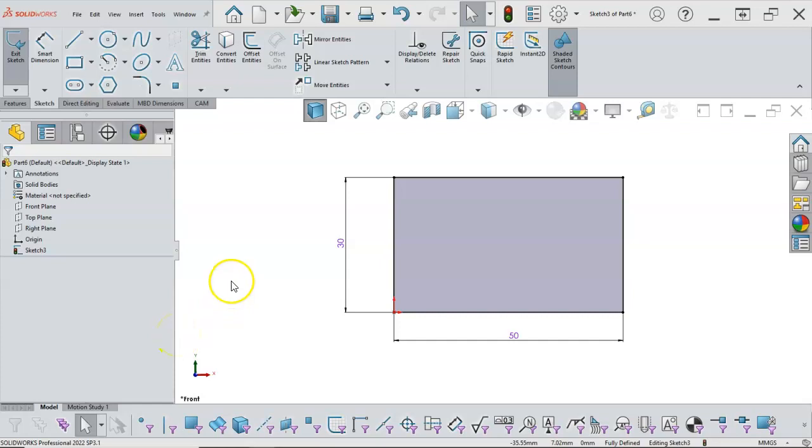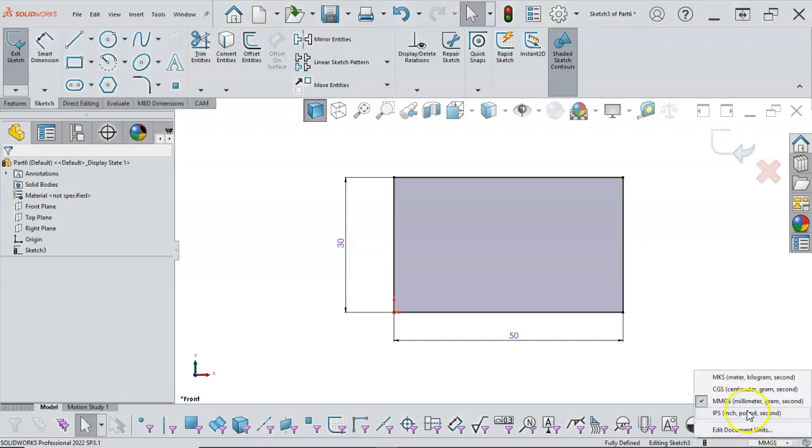Okay, so I think I started with changing and exiting out of a sketch. If I realize I'm in inches and I look down and see that the sketch is currently in millimeters, if I change that, that will kick me out of the sketch. If I exit the sketch, or accept and exit the sketch, usually it's going to be an accept, because exit will ask you if you want to discard the changes.